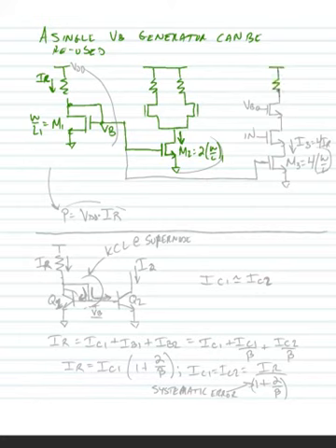And of course we could have another amplifier, maybe a cascode amplifier. We'll look at cascode amplifiers in more detail shortly. And we're biasing this cascode with a current source. We're going to tie it to that same VB node. And maybe we make M3 here equal to 4 times W over L1, in which case the current flowing through this branch, I3, would equal 4 times IR.